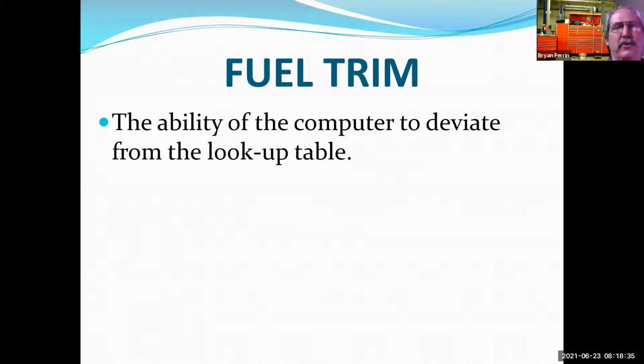But when I go back to, wait a minute, we're adjusting on time. The computer takes away on time based on what the O2 sensor sees. And we know we're running lean out the tailpipe, and we know the O2 sensor is good. So now you've got to start thinking, why would the computer take away on time? Well, the O2 sensor sees all of the cylinders on that bank, not just one. It's an average. So now let me start looking to see, is everyone equal? And like I said, you get some interesting stuff, but that's the real world.